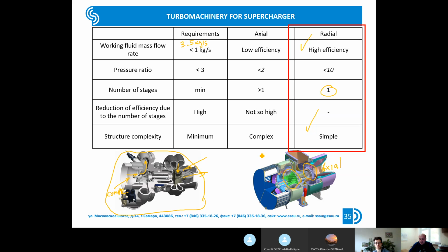These turbocharging systems are produced by ABB company. And why does this system use an axial turbine? It means that the mass flow rate through this turbine is rather high. And if your mass flow rate is 3-5 or more kilograms per second, it will be more suitable for you to use an axial turbine, because this type of turbine provides better efficiency than a centripetal turbine.